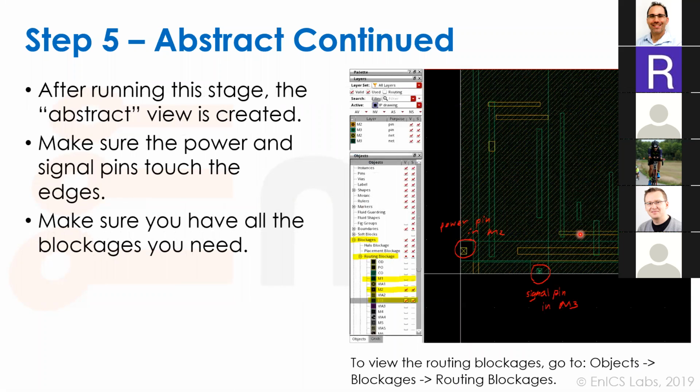But this may have had an extract or something on M2 and M3. Yeah, this is just an old example that Roman and I did a while ago. So I think this is not good. Maybe with one macro it's not an issue, but if you, for example, have several hundred of these macros, all of these LEFs are consuming a footprint of the memory, and maybe the router even considers somehow these lines. I don't know. And it's also not clean, and it makes other things hard to debug. You should see just one layer of blockage, and you should see your pins.